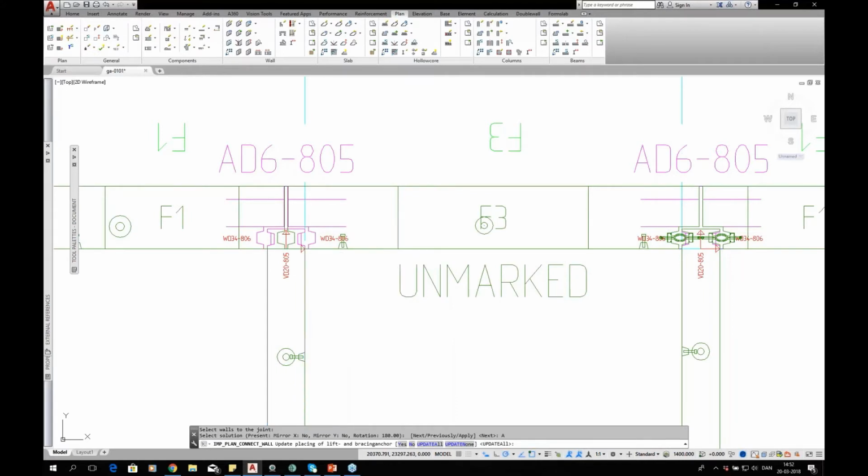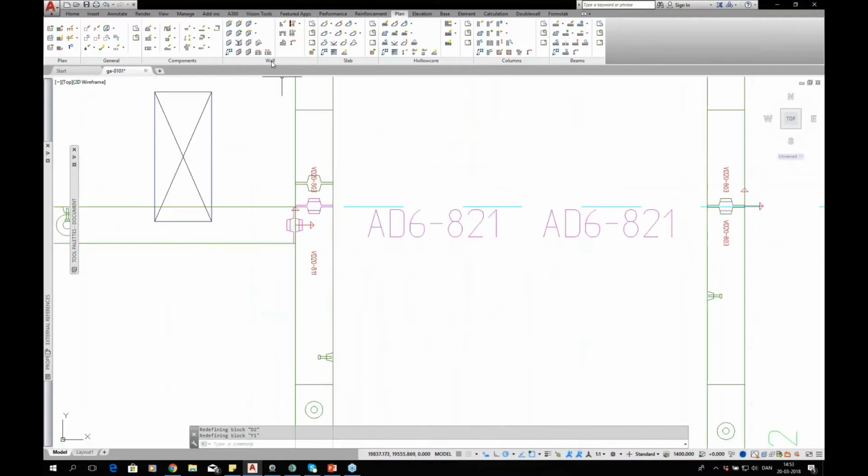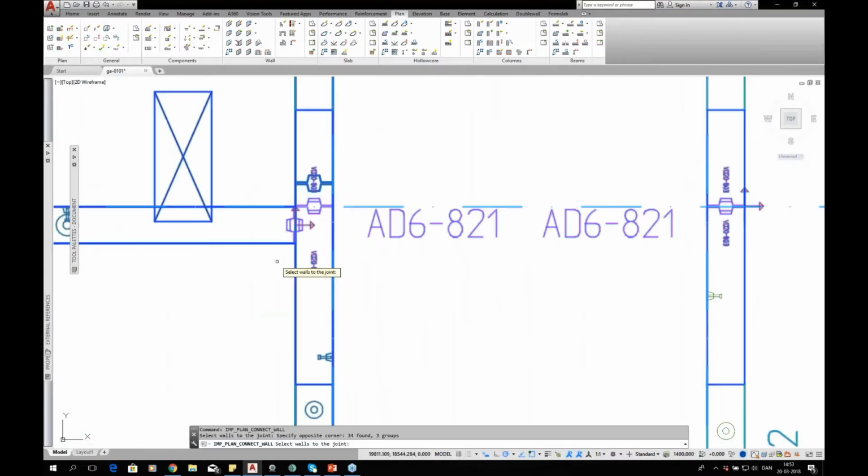So in this case, when I do this, it updates this, recalculates center of gravity for 3 elements, and also puts in approximately 10 wire loops for the solid wall, 5 wire loops for each of the sandwich panels here. So there's a lot of work being done and recalculation being done in the database. So that is perfect. And of course, we save tons and tons of time not having to do this ourselves. Let's just do this connection down here as well.